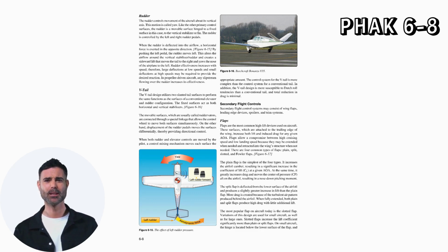Rudder effectiveness increases with speed. Therefore, large deflections at low speeds and small deflections at high speeds may be required to provide the desired reaction. In propeller-driven aircraft, any slipstream flowing over the rudder increases its effectiveness. V-tail.